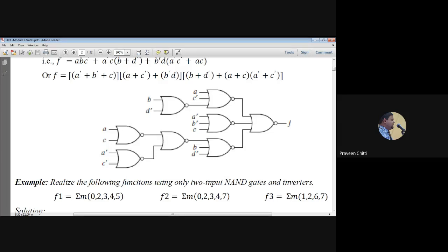All of you can write it down. You write down this procedure for designing minimum 2-level NAND circuit. I am giving you NAND first. The same thing you can apply for NOR, and then we'll see what to do for multi-level circuits. I am giving 2-level first, right?